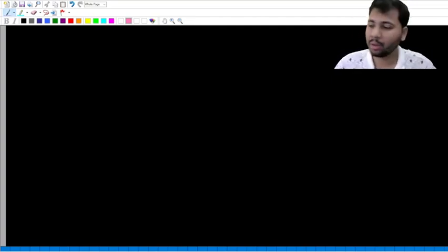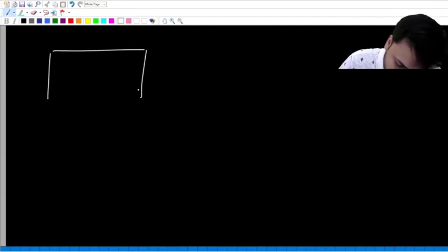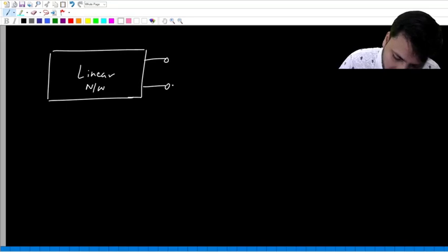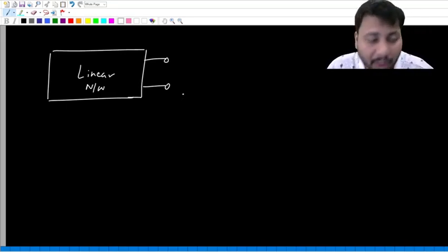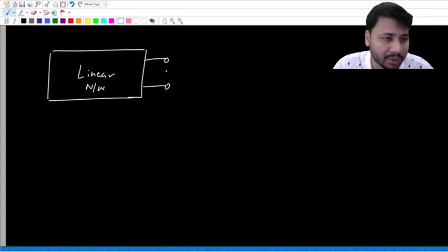So when can we use this Thevenin equivalent? We can use Thevenin's theorem when you have a linear network that has only one port, and if you are not interested in voltage and currents inside this linear network. Generally outside this linear network we connect a load resistance, but it is not compulsory that you should always connect a load. You can connect anything outside this linear network.